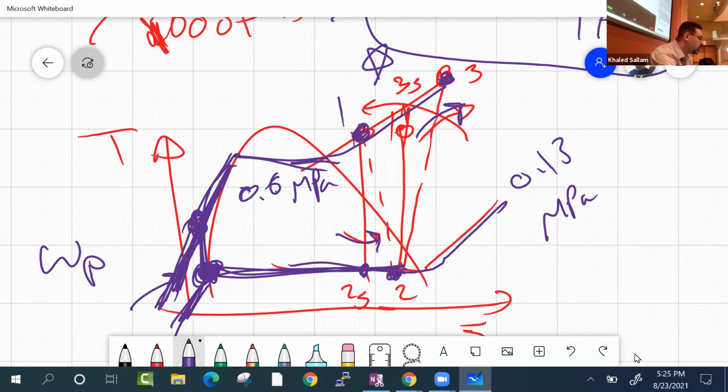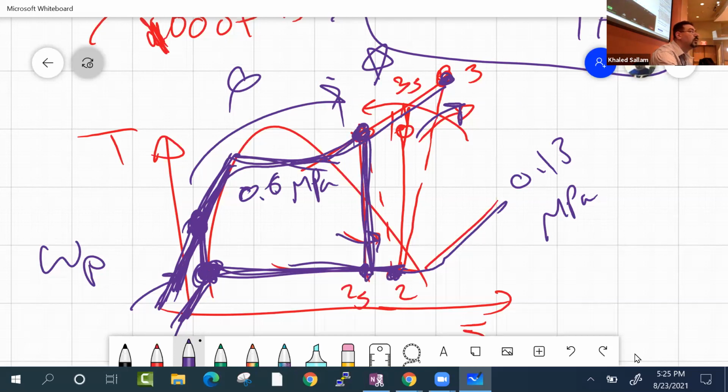Okay, so now once you are here and you reduce the entropy, then you come over here with heat, not work. So that is the Rankine cycle. You are turning that heat into work. And the price you pay besides this is that you have to reject this so that you can go to this point and start the cycle again. So we add Q added, but we have to reject Q rejected so that we can continue the cycle.